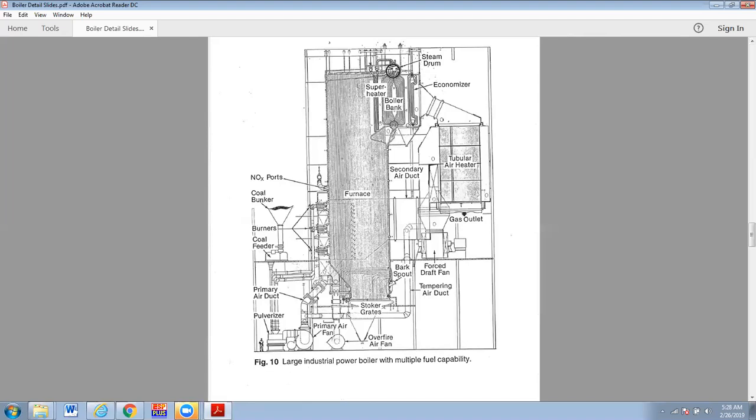But this drum is called the mud drum, and it's because any sediment or anything that sloughs off the tubes, anything fairly heavy, is going to settle down to the mud drum. And so we do separate blowdown. We do what they call bottom blow, which usually comes from the mud drum, and headers that are down here on the bottom can also accumulate stuff.